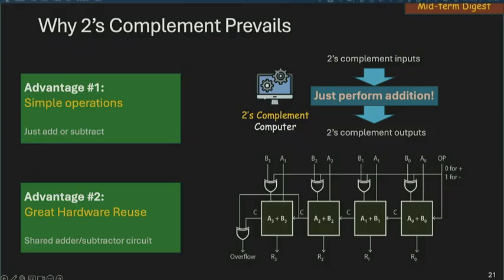In a full adder, the longest path will be something like going through the OP and then go through these 4 stages, right, until reaching the overflow. Or probably you start from B0, depending on which one has a longer path inside the full adder. So this could also be one of your long paths, right? And that just involves so many stages. If you have a 64-bit adder, within each adder, there are 2 gates, so 128 levels. And that is just too much for realistic circuits.